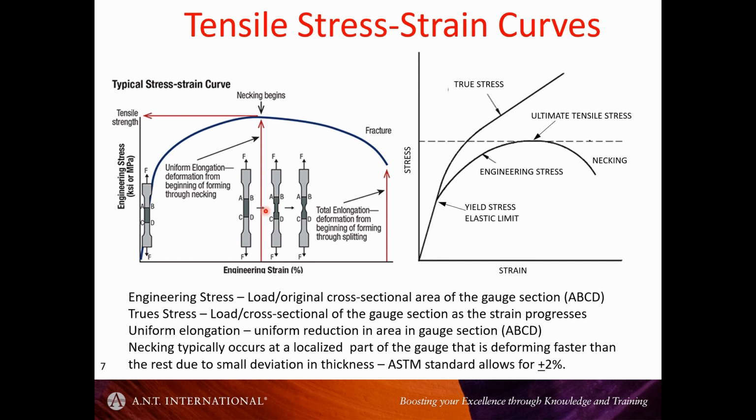Once necking starts to occur, it becomes much more difficult, and typically in tensile specimens nobody tries to calculate the true stress once this more severe necking is concerned. So all along, because the gauge is elongating, because of constant volume, it has to be thinning at the same time.